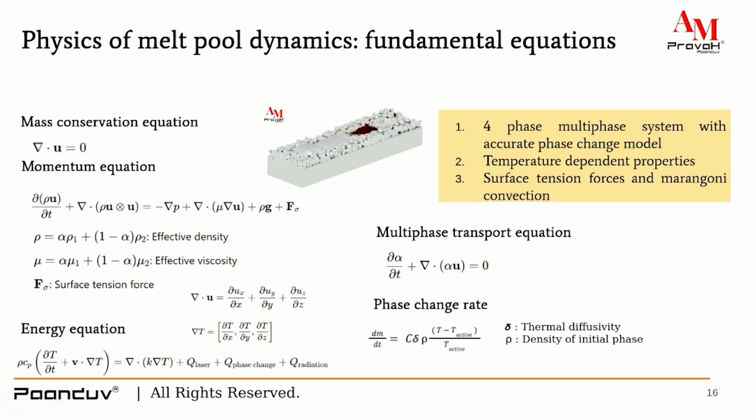Apart from that, when we study this phenomenon, we will see that phase change is also taking place here. So a certain part of the heat will go into the phase change. And where will the heat come from? It will come from the laser. So this is the heat source, which is going into radiation, and it is going into conduction, and here it is convection.